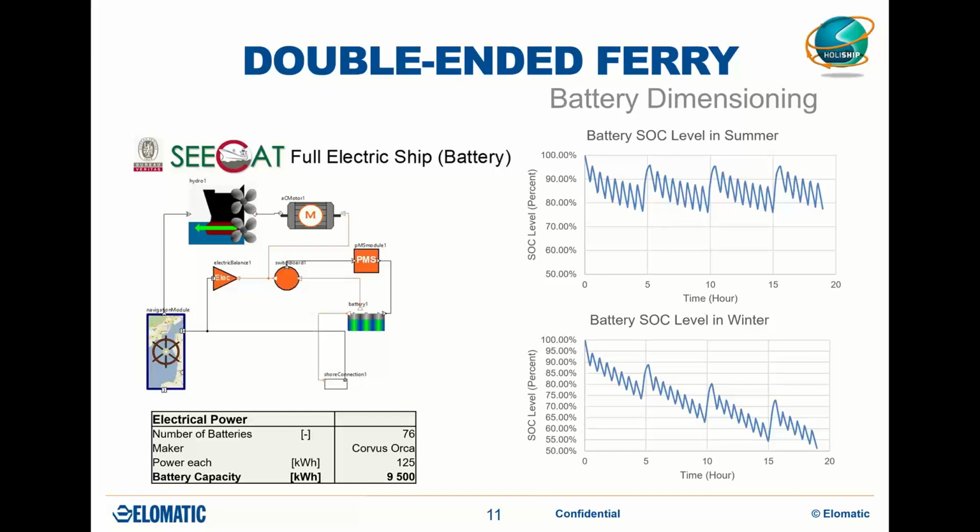In addition, we made a performance comparison between fully electric, hybrid, and diesel generator options. And this comparison revealed that the energy demand of batteries is lower than in diesel, because basically batteries can use almost 90% of received energy, while diesel can only utilize somewhat 40%.